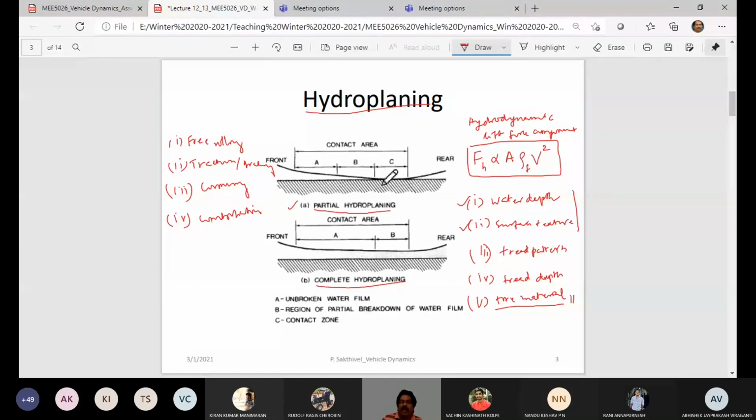So if I have a lesser contact surface, like only the C zone of the contact patch, we have already seen we will have an adhesion zone, a sliding zone, and so on. So if your contact patch length from LT reduces to only this much length, the generation of traction here is so much further limited. So it is going to reduce the tractive performance, and this will be more pronounced on truck tires. So as truck tire traction reduces, you would see more consumption of fuel.